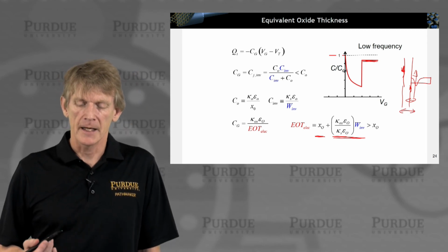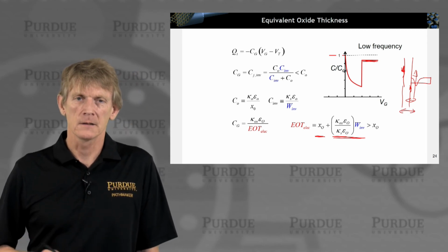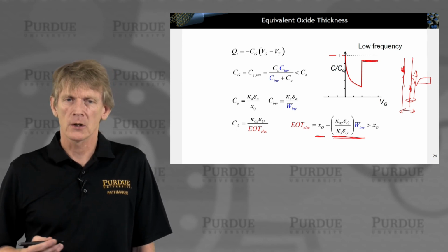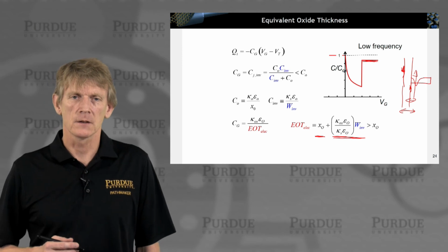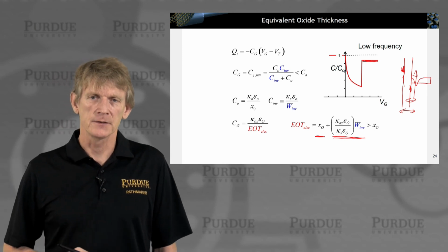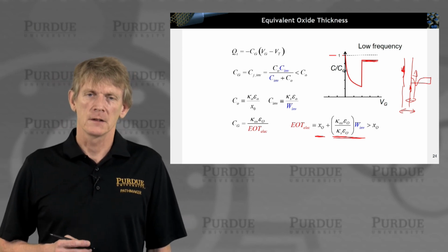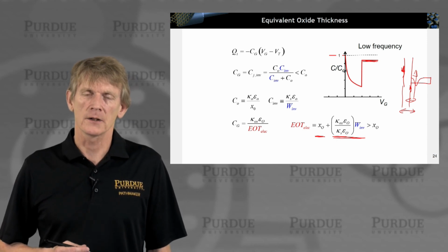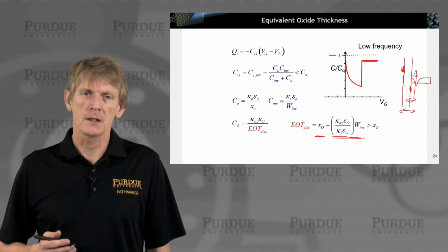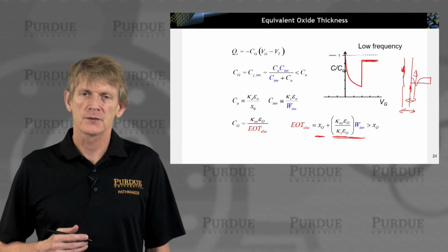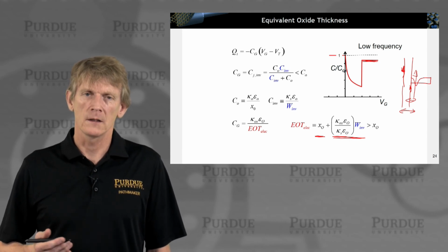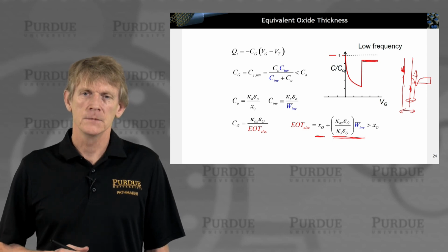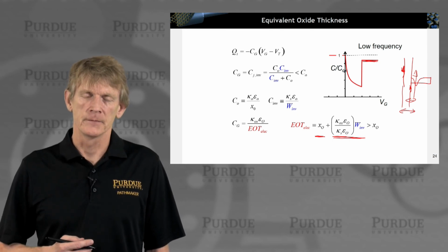And that term is larger than the oxide itself. So when you go to a conference and talk to experimentalists or theorists designing transistors, they talk about an EOT, which is the equivalent or electrical oxide thickness. That is what they mean, and that really describes, in a sense, also the width of the electronic channel in which you do have charges distributed.